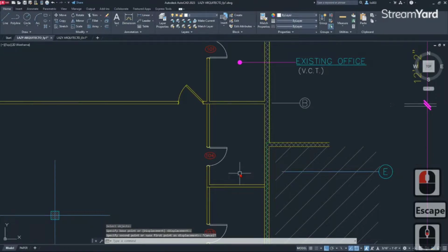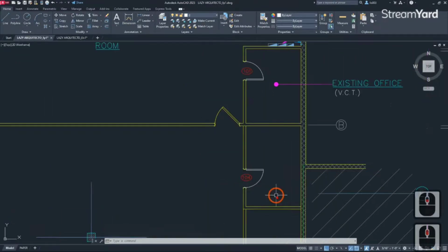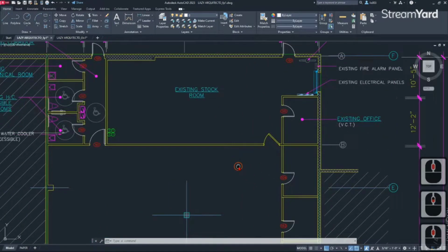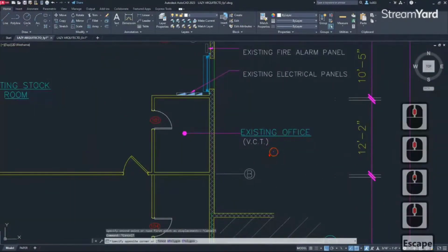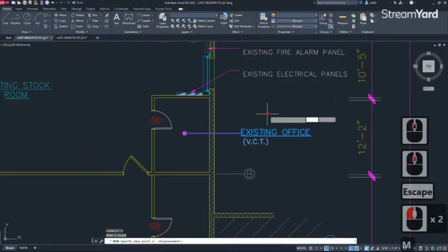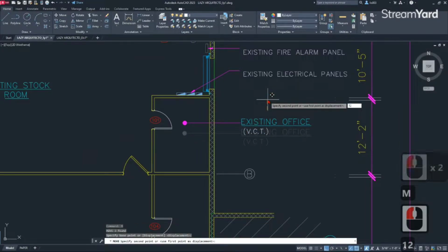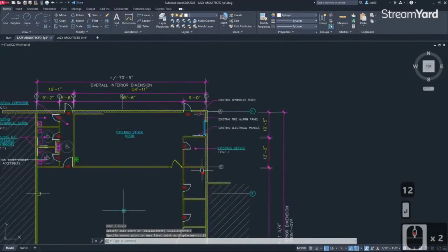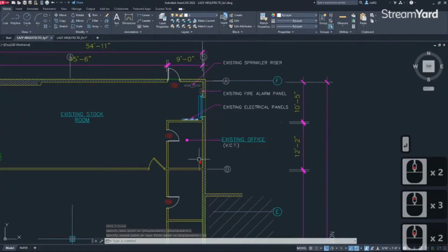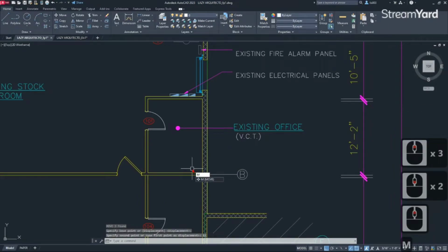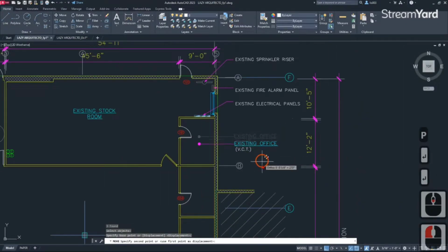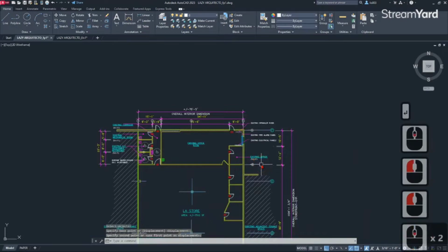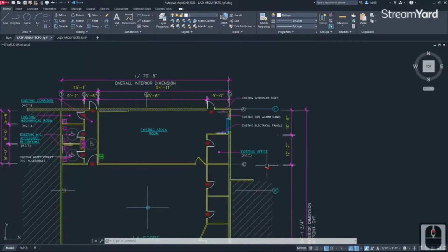So that's the previous tip for today. Previous works with most of the commands: move, stretch, and so on. For instance, if I'm selecting these objects, I'm going to move them up 12 inches, like so. Of course, this is a simple selection again, but if you did a more complex one, you can simply use the move command again and do P for previous and press enter. That way you will have your previous selection, like so. So very powerful. I use the previous option every time with any command.